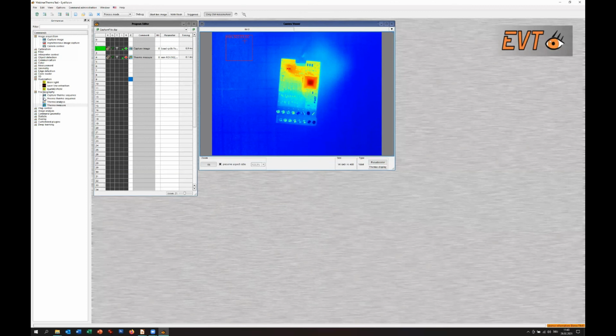These cameras are always made for specific wavelengths, and if you look at the temperature coefficient of the part you are looking at, you can define which camera you need. You cannot say, oh, I buy a thermal camera, and then you maybe see nothing because it works in the wrong wavelengths. It's not so easy.